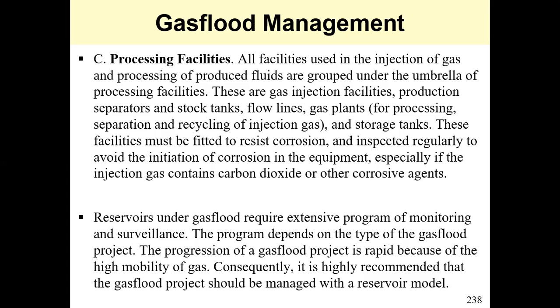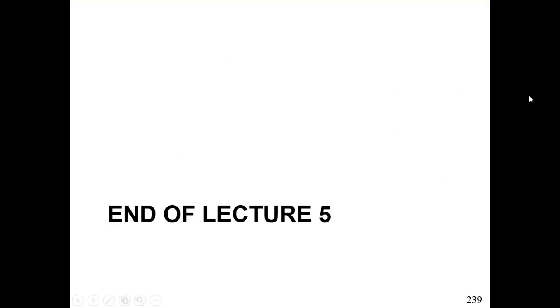Reservoirs under gas flood require an extensive program of monitoring and surveillance. The program depends on the type of gas flood project. Progression of gas flood projects is quite rapid due to high gas mobility. Therefore, it's recommended that the gas flood project be managed with a reservoir model.